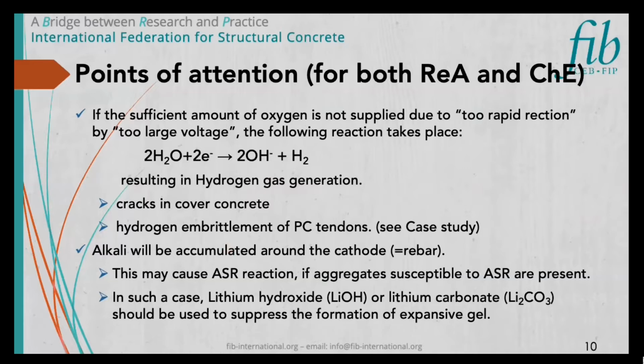One more important thing is that alkali will be accumulated around the reinforcing bar. This may cause alkali-silica reaction if reactive aggregates are present in the concrete member. In such a case, lithium hydroxide or lithium carbonate should be used as an electrolyte to suppress the formation of expansion gel.